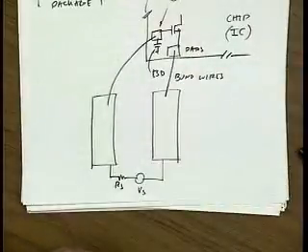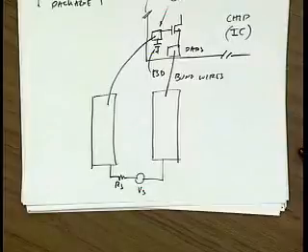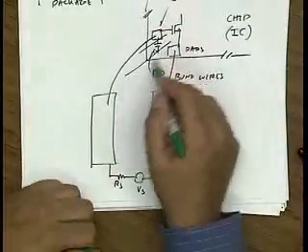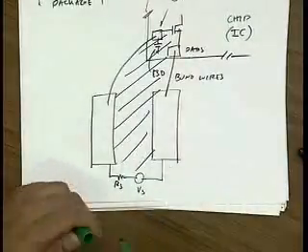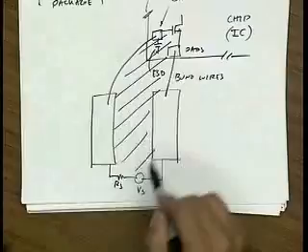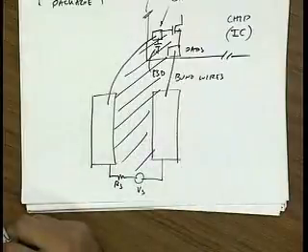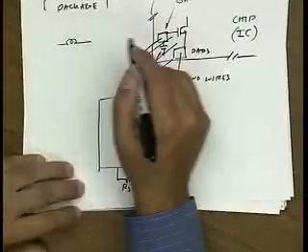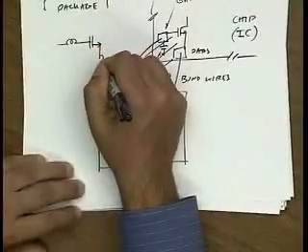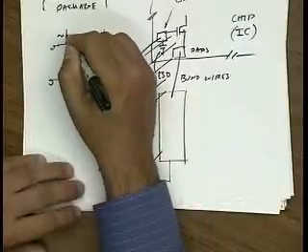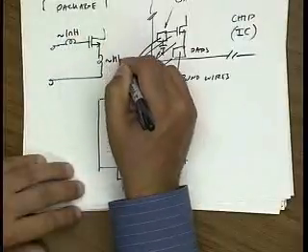And if you see this loop, it's a physically large loop. And if you run a simple calculation, you can see that the magnetic flux in this loop generates an EMF which is substantial. And in circuits, we model that by just putting inductors in series with these terminals. Okay? And these inductors are on the order of nanohenries. Okay?